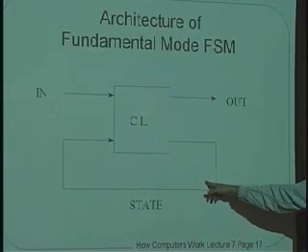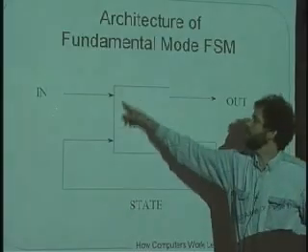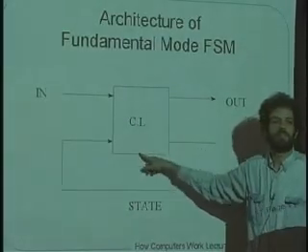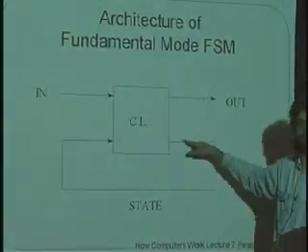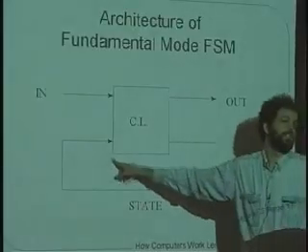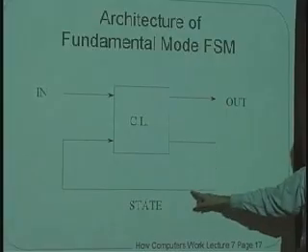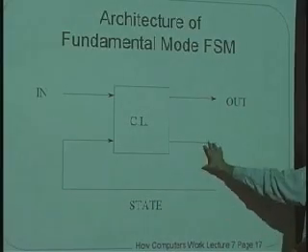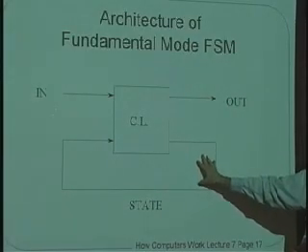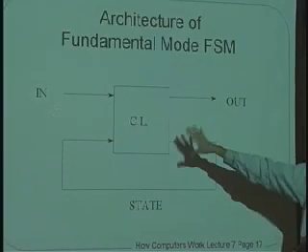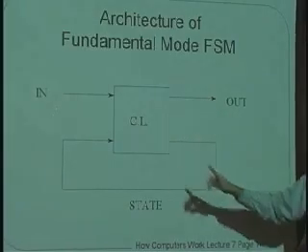And what was the circuit that we just built? We used a selector here, and we had the output and the feedback be the same signal going back around like this. And we had no synchronizing element in the loop because we're trying to build that element. And so ultimately we build it just out of some logic and wire for feedback.